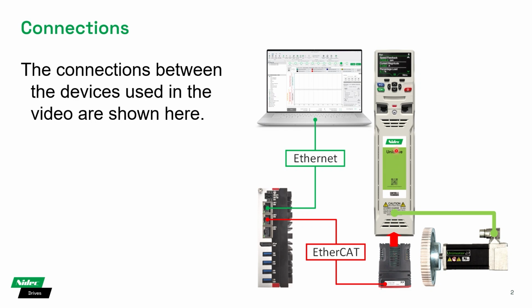And then at the other end of that EtherCAT connection, I've got an SI EtherCAT interface, which is plugged into a Unidrive M700. Now we do have some other drives which actually feature an EtherCAT interface by default, so that's Digitax HD M753. The setup for it is identical, it uses the same steps to follow, just a slightly different ESI file when you're running in the TwinCAT environment.